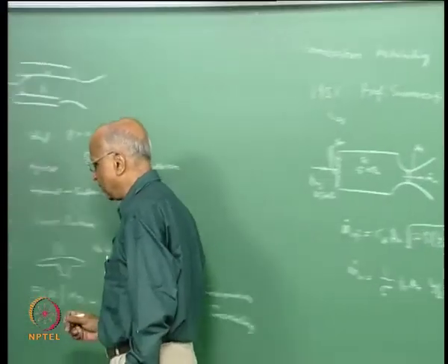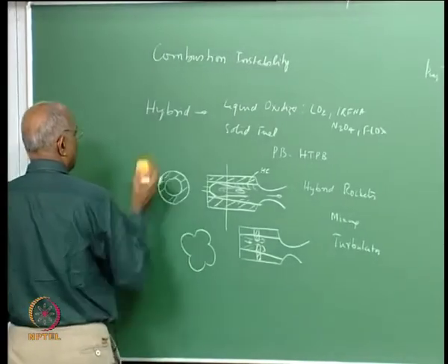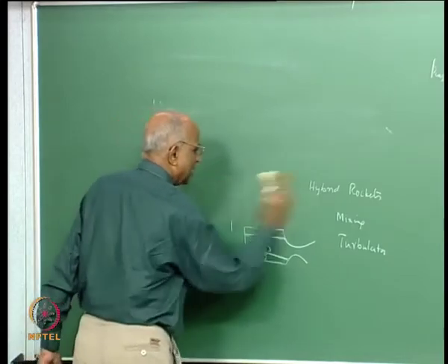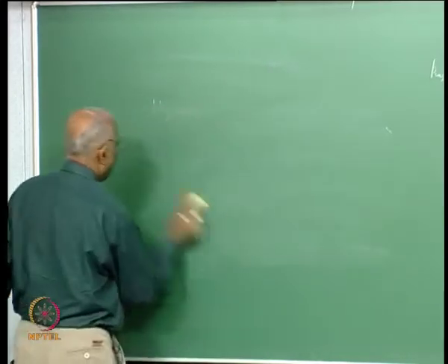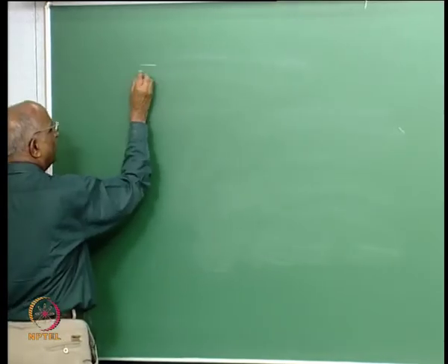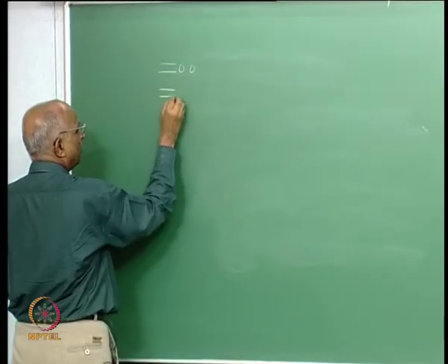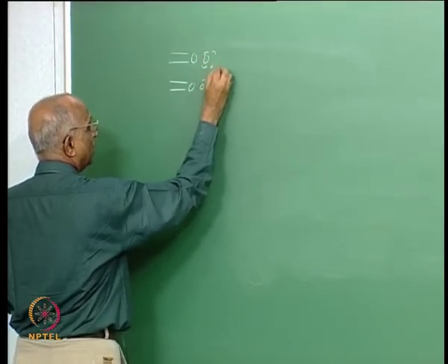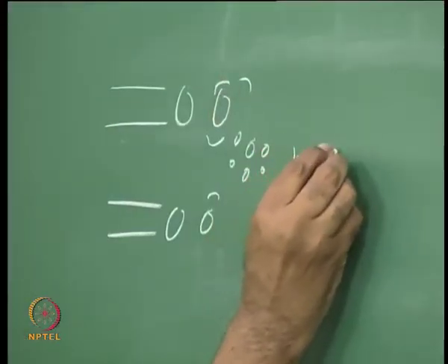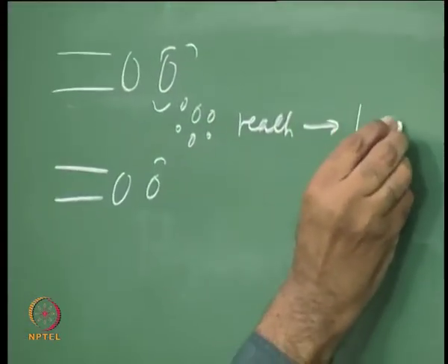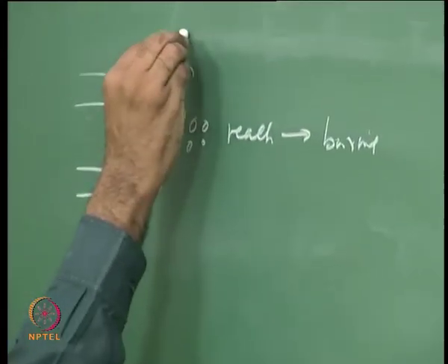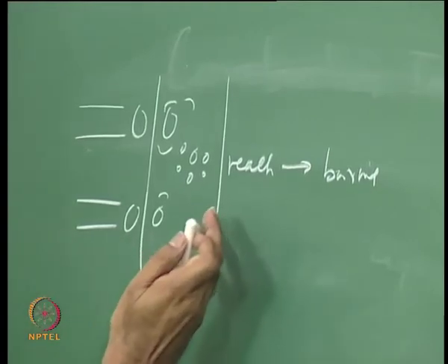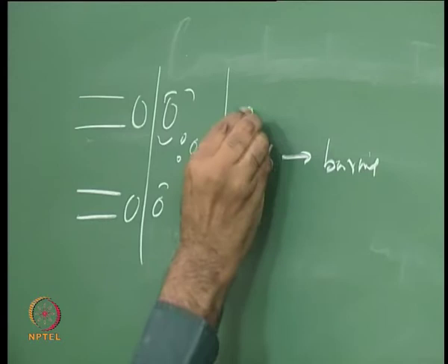Let me go back on that side again, because this point is important and this will be central to all our discussions. All what we are saying is there is a certain delay, because whenever I inject something, maybe I inject a liquid, it breaks into droplets, maybe fuel breaks into droplets, then it evaporates, the fuel and vapor mix together, then they react, and then out comes the burning gases. That means this occupies quite a tremendous amount of time. The vaporization takes time, atomization is fast, reaction may be fast, mixing before that also takes some time.